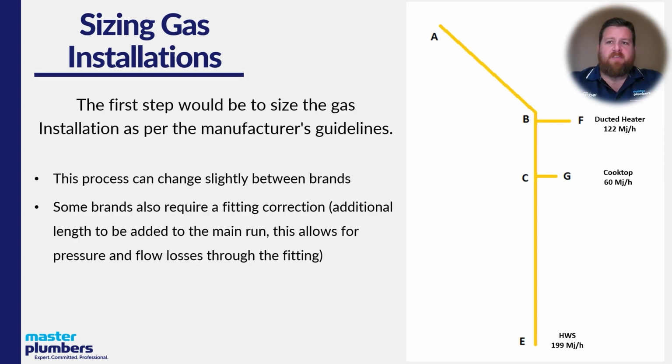So when sizing our multi-layer pipe installations, it's important to understand that the manufacturer's sizing guides differ slightly in their installation practices, and particularly their megajoule capacities. So it'll change slightly between the brands. Some of these brands require fitting corrections, some of them don't require fitting corrections. So it's important that you understand the piping system that you're actually working with.